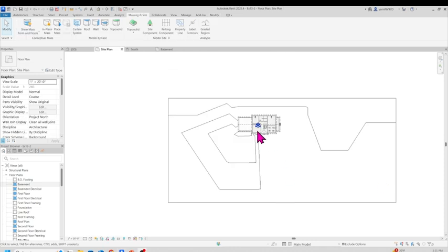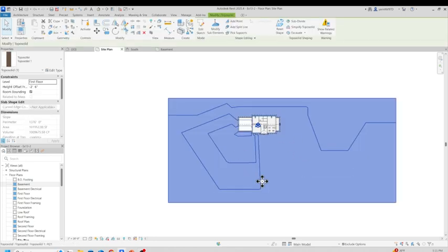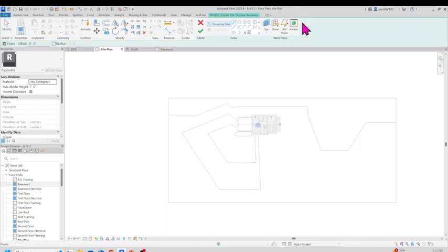All right, let's go ahead and put a driveway in. So from a site plan, go ahead and select the topo solid. Basically, clicking on this side here. So it's like this, and then your ribbon changes. From up here, use Subdivide. And then your ribbon changes. We have the drawing tool, the drawing tool we're going to use.